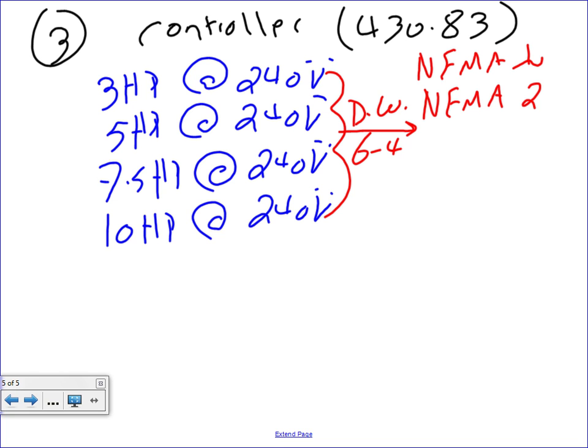Magnetic starter, guys. What we're sizing right here is this contactor. Everybody's there? We're sizing this contactor so you can push a button and start and stop the motor. That's what a controller is. Chris, do you remember what you did with Gary with push buttons, when you did the magnetic starter on the wall? Push button station, you push the button, start and stop the motor. That's what we're sizing. Good point. Okay, NEMA 2.